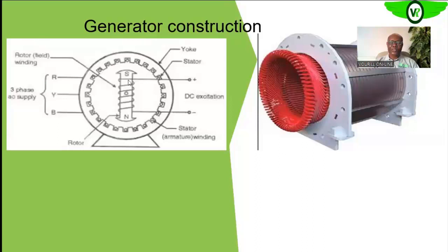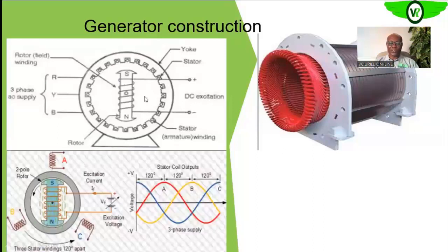So now if you look, you also see that we have the rotating field in the middle. So we also have windings in the rotating field. Are we getting it? So to magnetize this, we need a DC power supply from the excitation circuit. So this one is on the rotor. So this is a rotating field generator. So once you have your DC voltage sent into the rotating field, okay? Remember, this rotating field is coupled to the prime mover. That is the rotating mechanical energy.